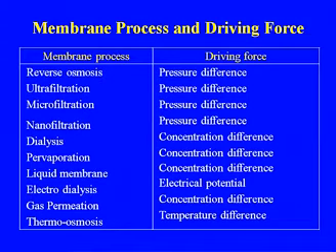Dialysis, the concentration difference; pervaporation, concentration difference; liquid membrane, concentration difference. Electrodialysis, the electrical potential is the driving force, and gas permeation, concentration difference. Thermo-osmosis, the temperature difference is the driving force. So these are the various types of membrane separation processes which we are using in some form or other in the chemical industry.